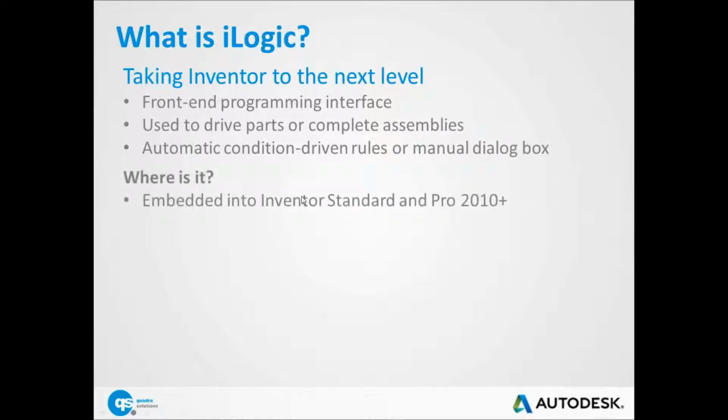So where is it? It's embedded into Inventor and Inventor Pro and is subsequently installed as such, so there's no need to download and install it separately. As I said earlier, iLogic was rolled out from the 2010 release, so if you're using Inventor 2010 or later, you already have it as part of the full product. Note that LT is not mentioned. iLogic doesn't come with any release of Inventor LT. Similarly, if you're using 2009 or previous, you don't have it either. But 2010 users and above, with Inventor and Inventor Pro, you do have it automatically.